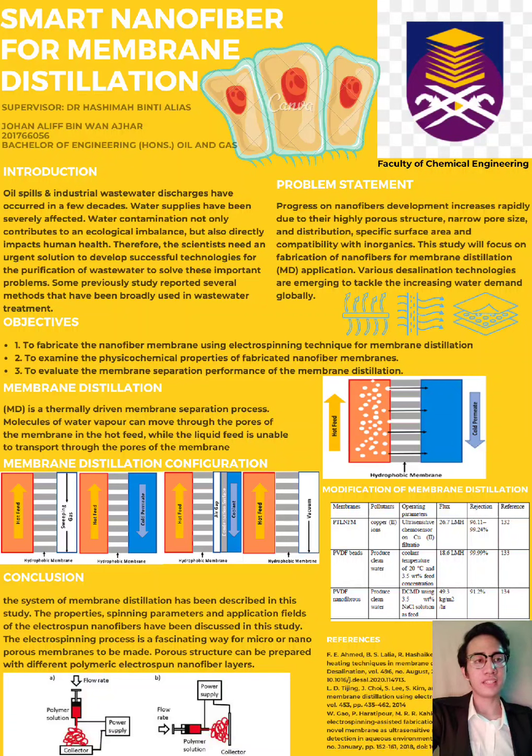Depending on the method in which the permeate side is processed, the membrane distillation process is divided into 4 configurations. First is direct contact membrane distillation, which is DCMD. Second, sweeping gas membrane distillation, SGMD. Third, vacuum membrane distillation, which is VMD. And last is air gap membrane distillation, AGMD. The various MD configurations have been thoroughly explained and reviewed in many articles. The contrast between the membrane distillation configurations you can see on the figure.